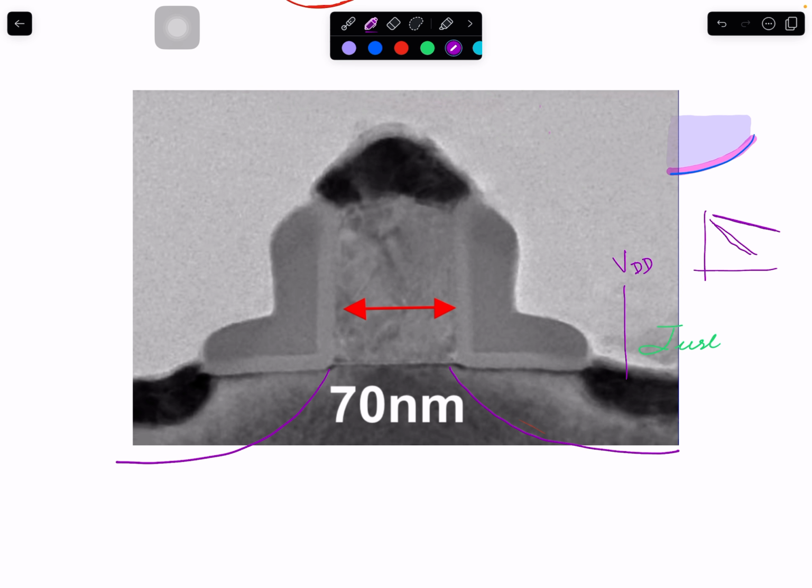Early on they would not want to bring it down, but the dynamic power, the switching power, was highest, and they had to reduce it because we were increasing the frequency. So we were switching the transistors a lot more, and this time we were putting a lot more transistors in the same place. So switching power was a major concern. So voltage didn't go down as much.